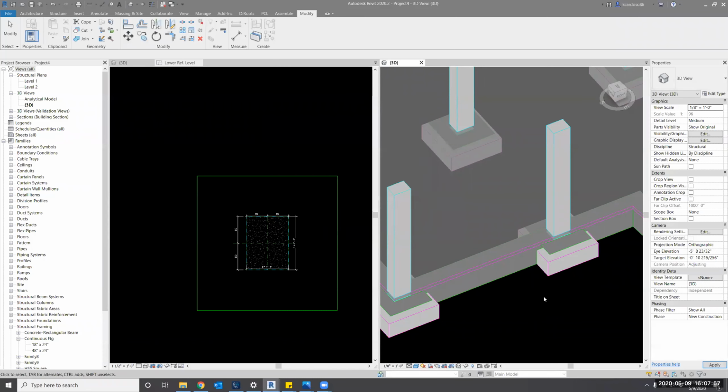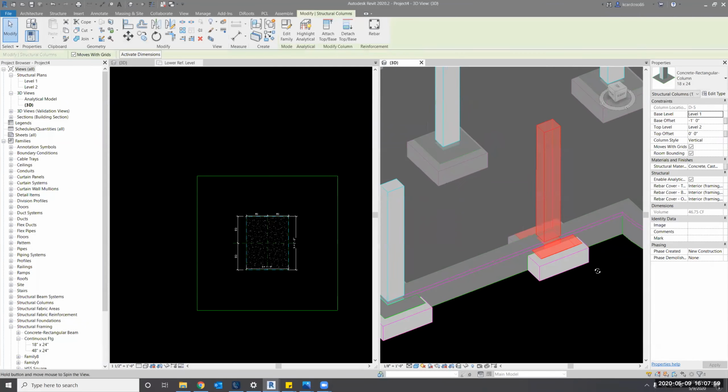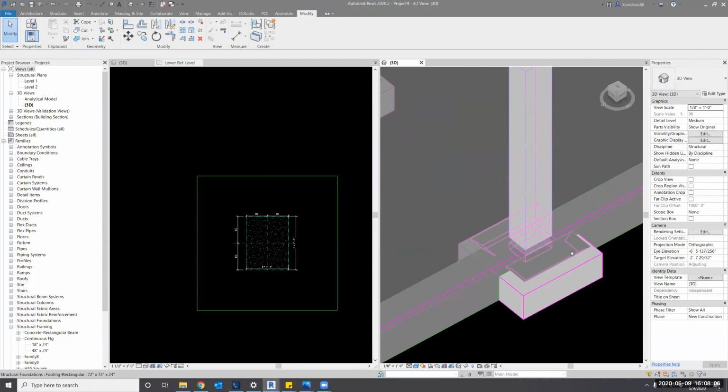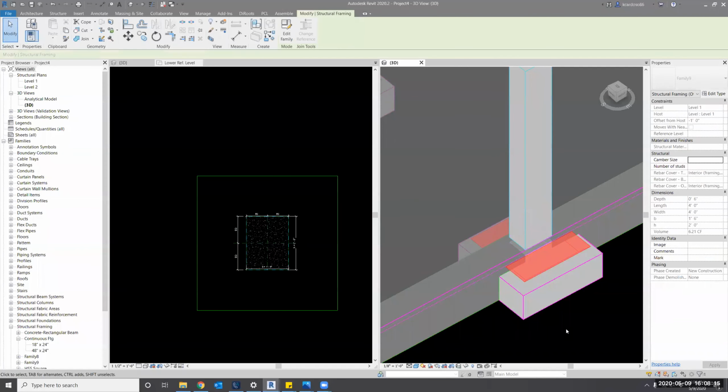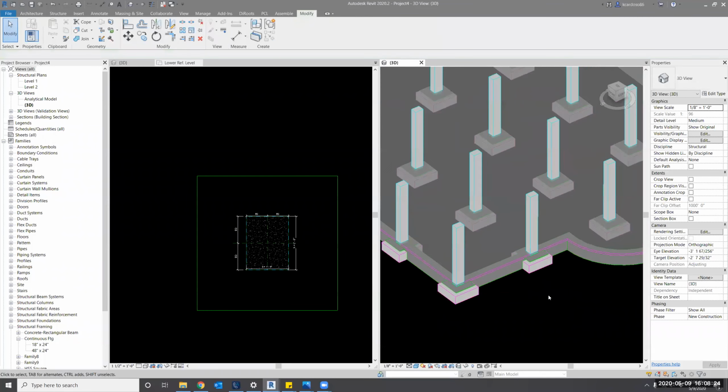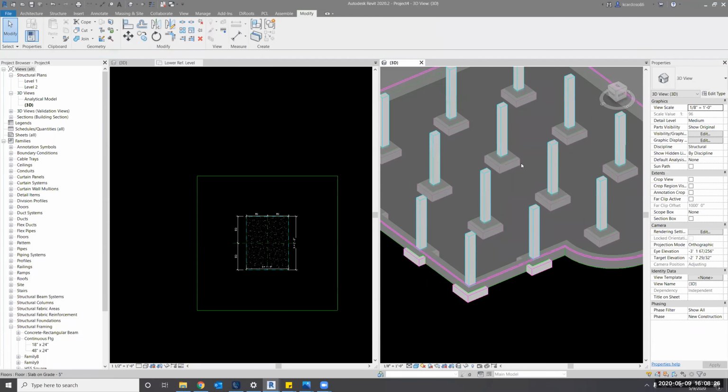Okay, so we're getting somewhere. The column is punching through this thickening. And we can select the thickening by clicking tab on your keyboard. The first hover is the host, the column. So now hit tab on your keyboard and click on it, and that shows you this nice little number of volume. So let's go ahead and switch the join of all these columns to the floors.